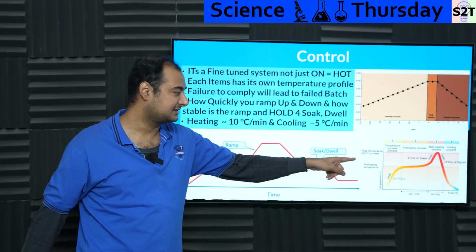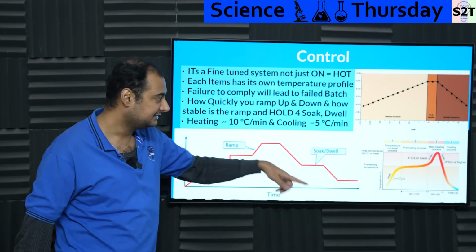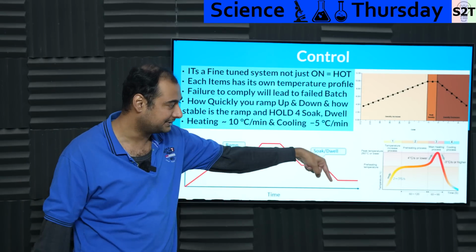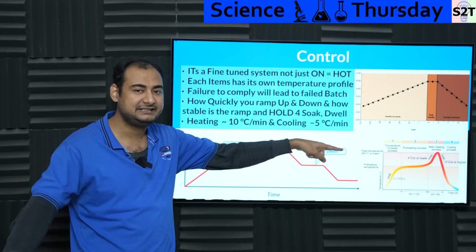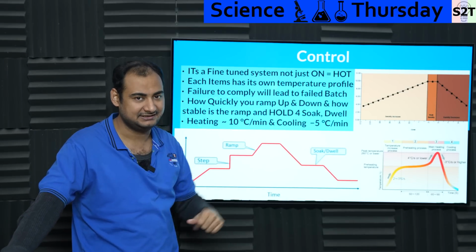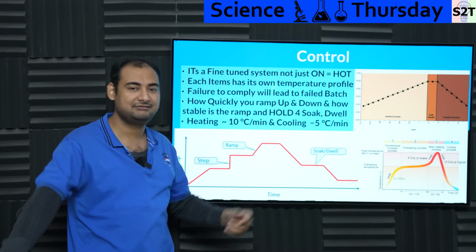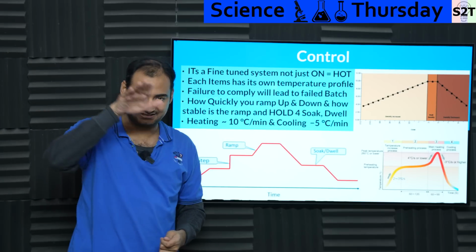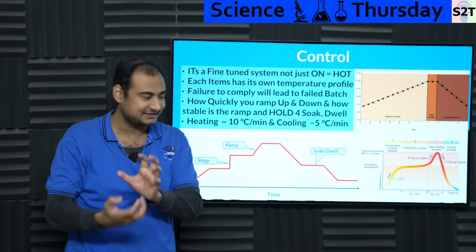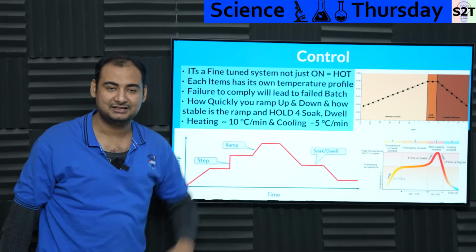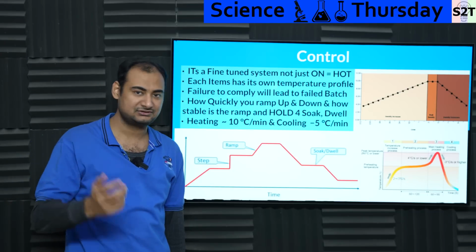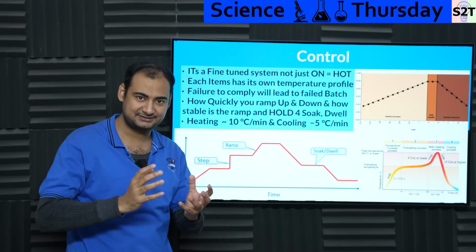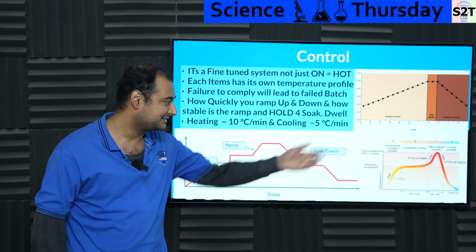Then you go to 4 degrees Celsius per second for about 60 to 90 seconds, and then your peak temperature crosses 260 degrees Celsius, then you drop it. Now, dropping you have to do at minus 3 degrees per second. You have to cool down fast, and that's why whenever you see PCB ovens, they generally have different segments, because again, the engineer will design a heating section that can give you 4 degrees per second very quickly without causing too much electrical wastage. But if they do that, insulated and designed properly, it will not cool down fast enough.